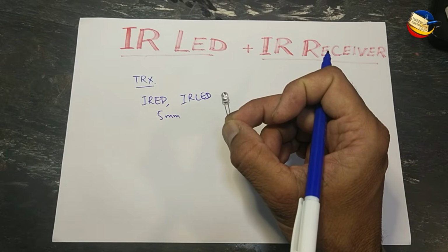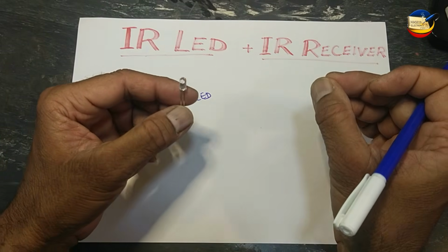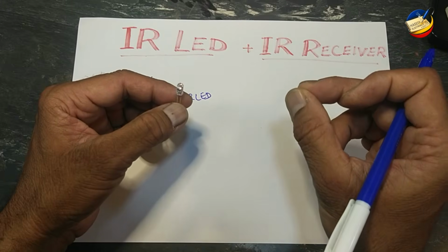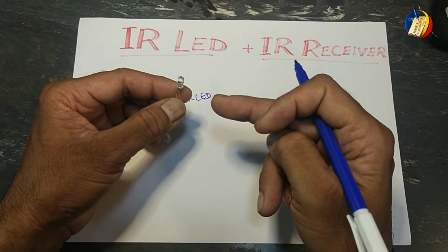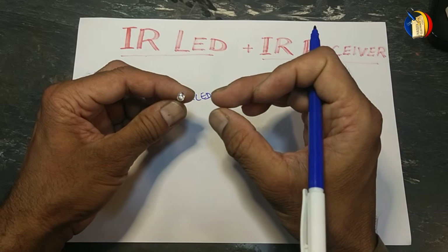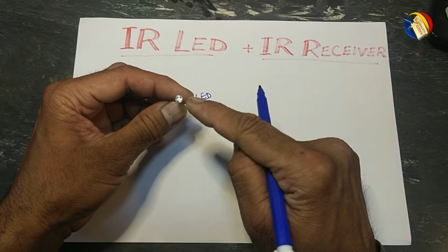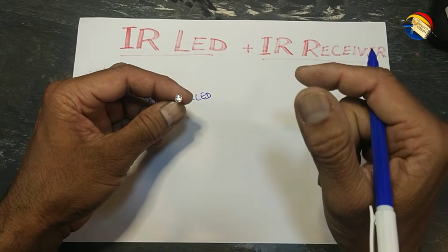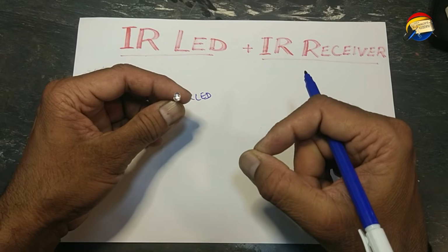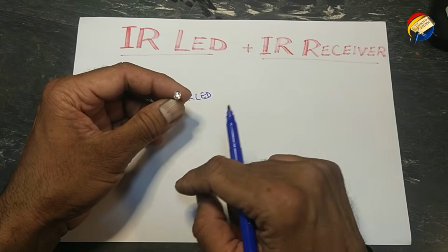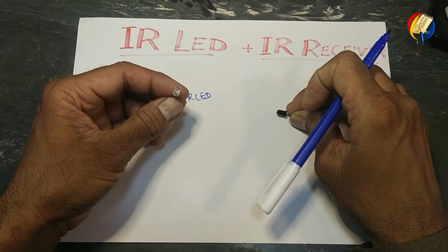But an IR transmitter will drop 1.2 volts to 1.8 volts, and a maximum of 100 milliampere current can be provided to this LED. It will not transmit any visible optical light. It will transmit infrared light. We cannot see its light with our normal eye, but we can detect it using a camera or a phototransistor.